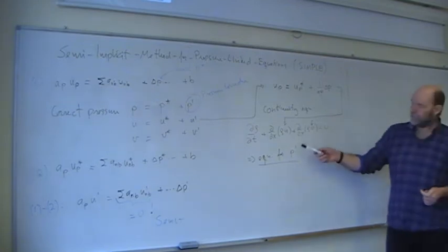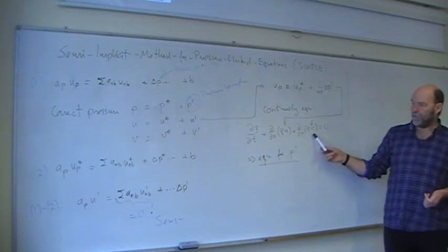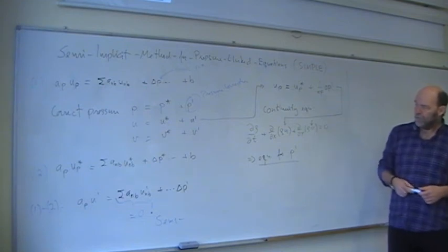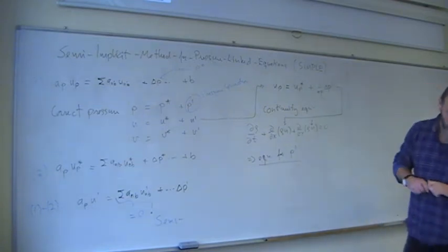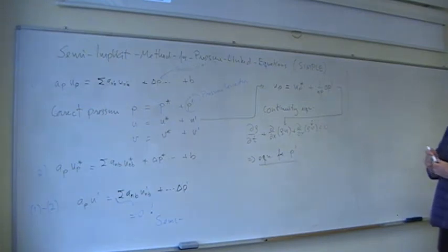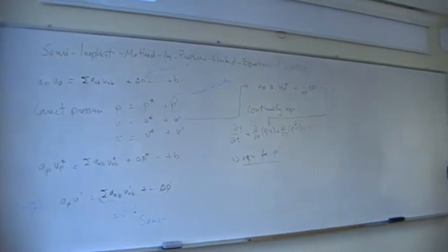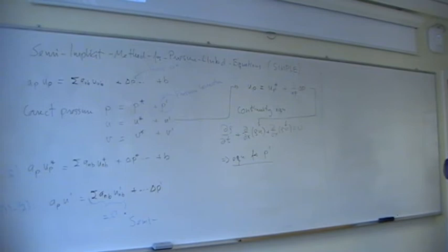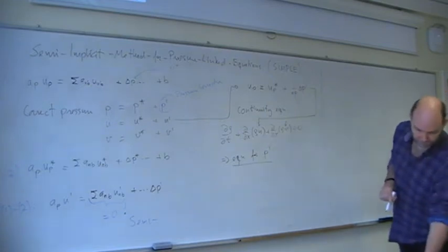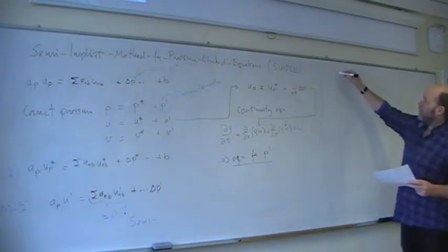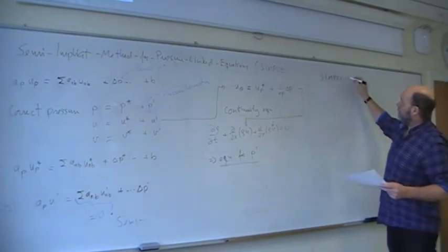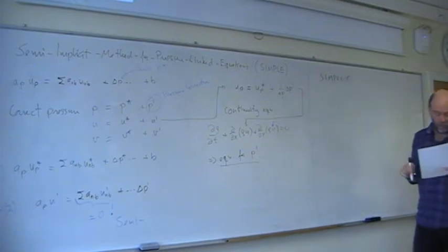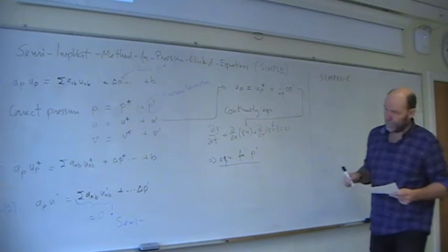How this equation actually looks will of course depend on how you discretize this continuity equation. So many ways to do that. After this one was invented, you immediately had a whole family of variants. Some of them quite smart actually. One, for instance, is called SIMPLEC. You do this equation here, but you do a trick.